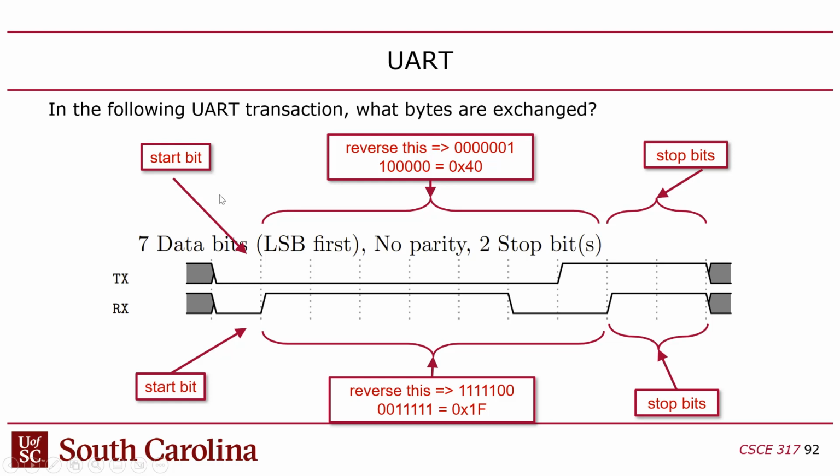Okay, so this is the same data. One other thing I want to point out is that the transmit and receive are shown here lined up. It's implying that 1 byte is sent for every received byte, and that doesn't have to be the case. This is just shown for convenience while reading these things. Generally, the transmit and the receive side are both independent, and usually they're not active at the same time. I mean, it's possible, but usually, as I mentioned, it's for terminals. So you're typing a command on a terminal and then hitting enter, and then you're getting data back. So a lot of times, only one of these is active at any time.